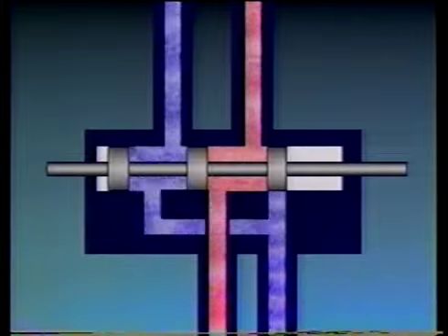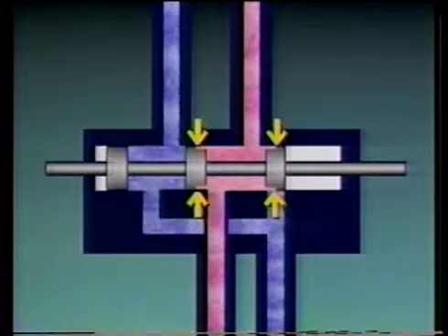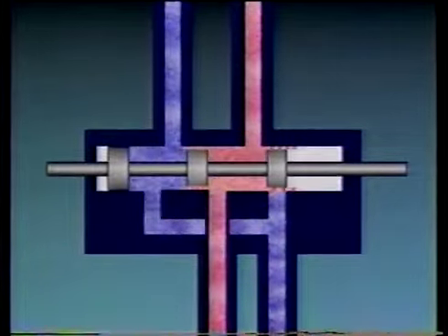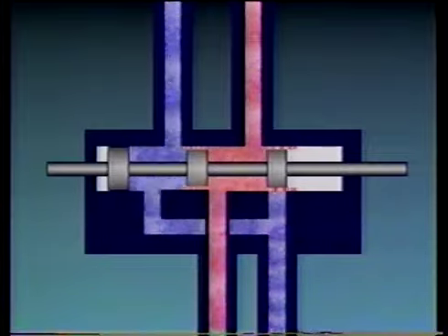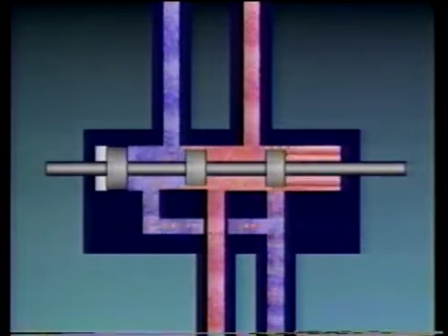Viscosity is also important because the fluid helps reduce leaking between close-fitting parts. If the viscosity is too low, the component will pass too much fluid through these clearances, and flow through the remainder of the system will be reduced. In addition, as the fluid passes through these narrow clearances, more heat will be created by friction.